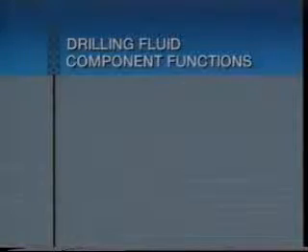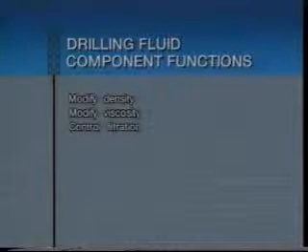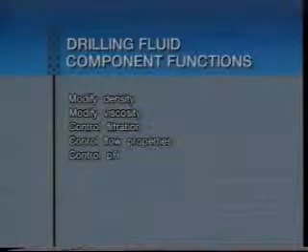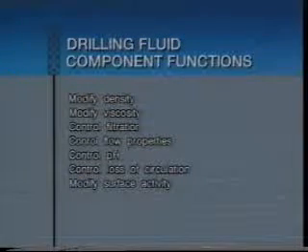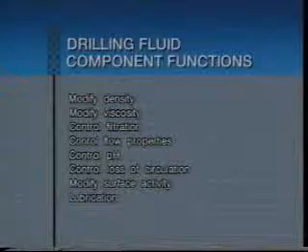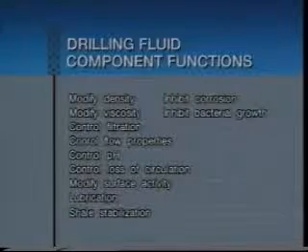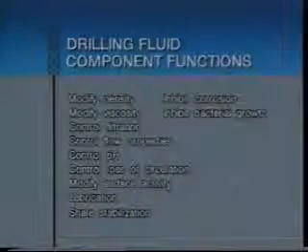The drilling fluid continuous phase, water or oil, may have components added to it to modify density, modify viscosity, control filtration, control flow properties, control pH, control loss of circulation, modify surface activity, lubrication, stabilize shales, inhibit corrosion, or inhibit bacterial growth. Let us look at each of these individually.